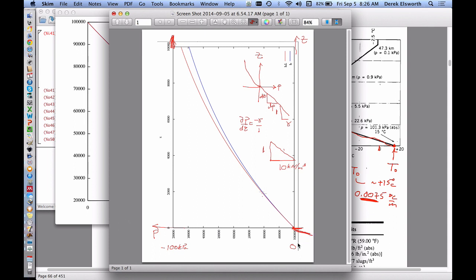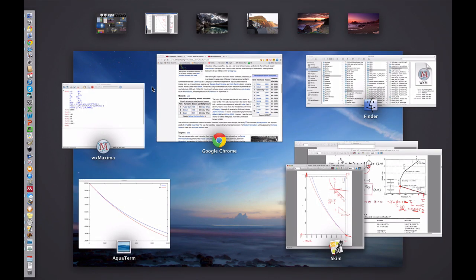And that's because the unit weights are a factor of 1,000 different from each other: the unit weight of air versus the unit weight of water. So it's always useful for us to think about this as being how the pressure changes in air as we go down here, because this is curved. In water, it would be straight, but in fact, in water, it would actually look more like this. It would be 1,000 times flatter than this gradient here, just by the relationship we understand. Okay, so that's useful to at least understand, hopefully.